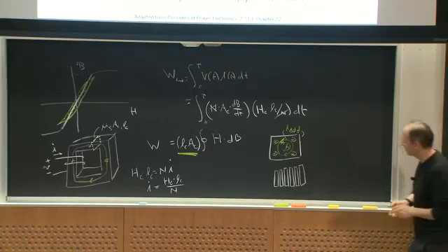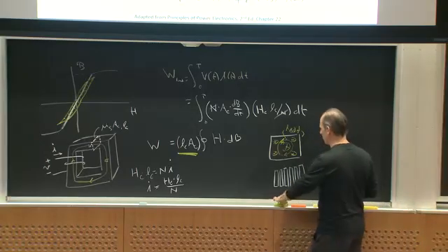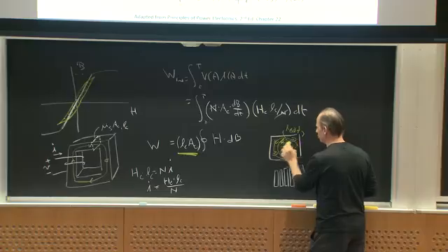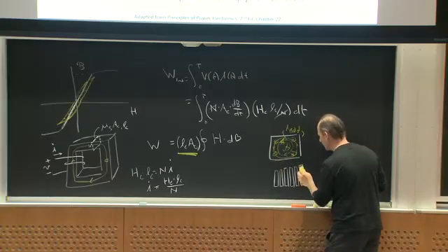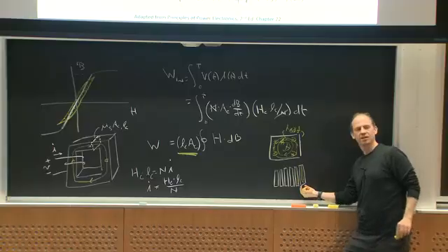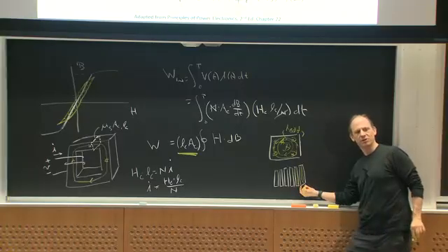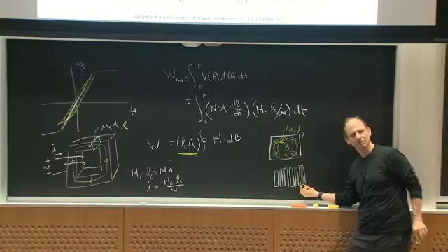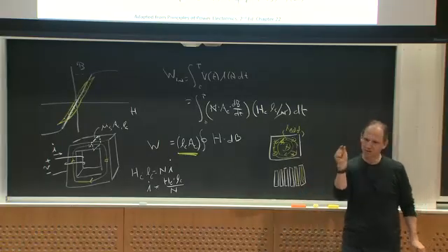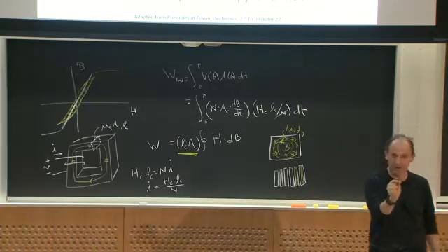The nice thing about this is that instead of this big eddy current being allowed to run around this huge loop and cause lots of loss, it's forced to circulate in these tiny little areas. As long as these laminations are thin compared to a skin depth, the eddy currents more or less cancel out and you don't get much eddy current loss. So you'll see a lot of 60 hertz transformers and electric machines are built out of laminations.